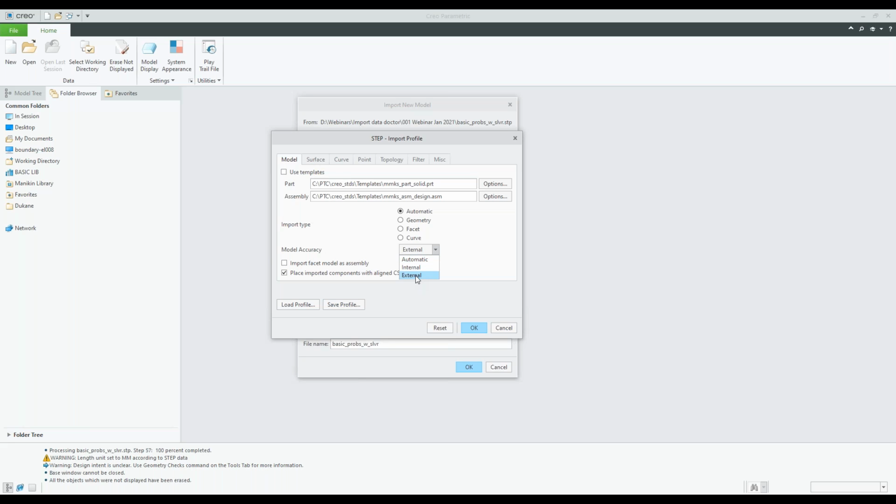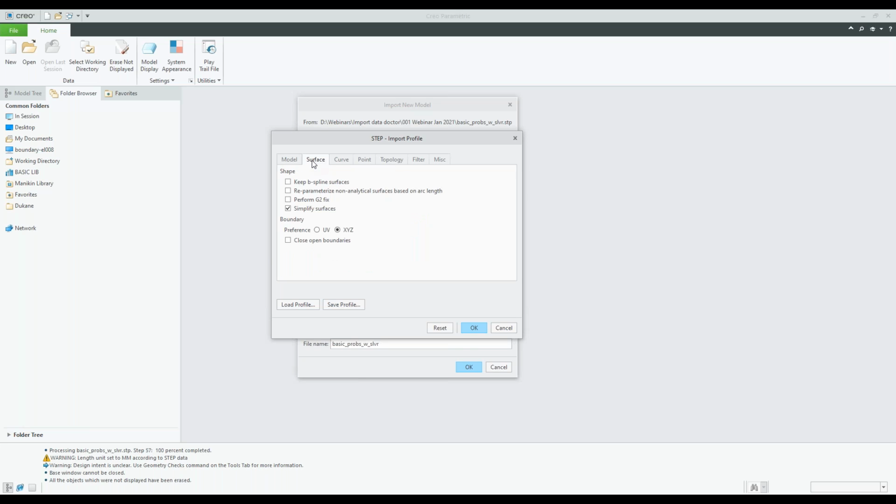I've done this a few times now and saved the settings, so mine is by default on external. Okay, then if we go through all of them here at the top, you can untick all of these. That one's default, we can leave that on. On this window, again, very important. I think if you start up Creo for the first time, or you import this, yield, close gap between surfaces, repair unsatisfied geometry, we don't want Creo to do anything at this stage. We're just going to investigate this model now.